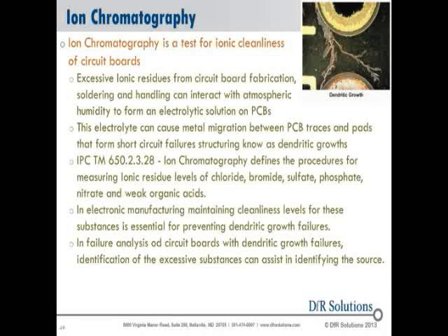If these residues are excessive, they can react with humidity to form an electrolytic solution on the surface of the circuit board that will support electrical current transfer that will drive metal migration, and what you will do is build these dendrite bridges, as they're called, or dendritic growths.